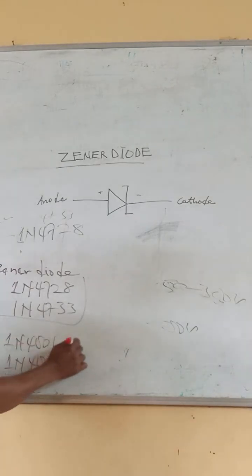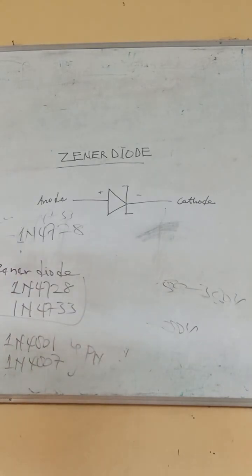If you see something like this, it is PN. So for PN and Zener that look alike, you will see a number there. You can get this number from the data sheet. If you see a diode and you don't know if it's PN or Zener, write that number, go to your phone, and type the data sheet of that number. It will tell you if it is Zener or PN. I'll still give you more numbers of Zener and PN later at the end of this video, different numbers that we can use to know if it is a PN diode or Zener diode.